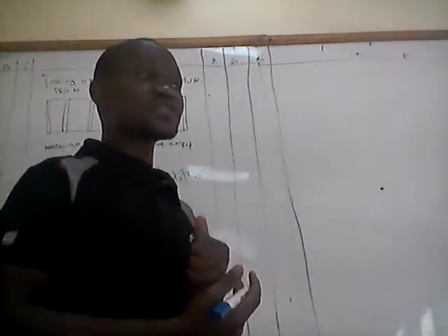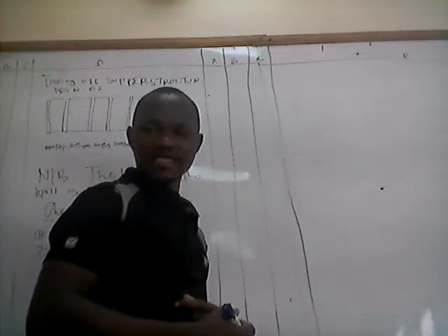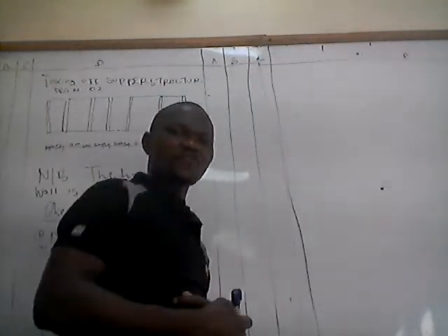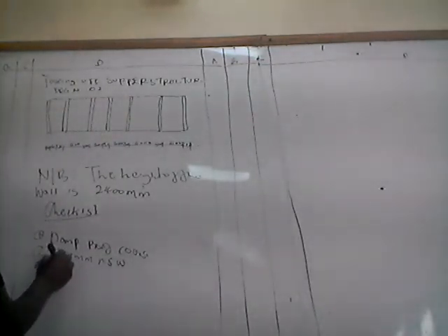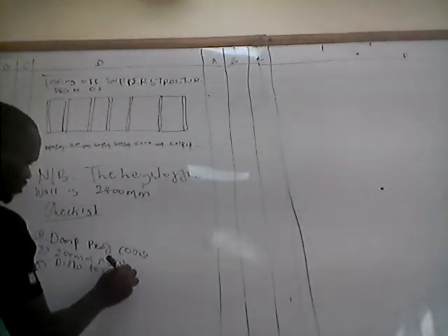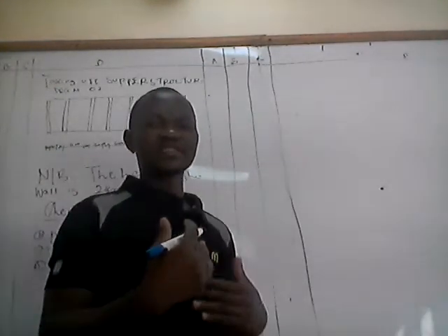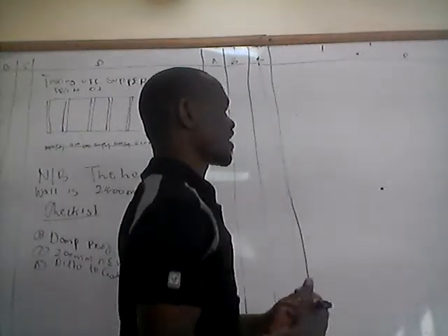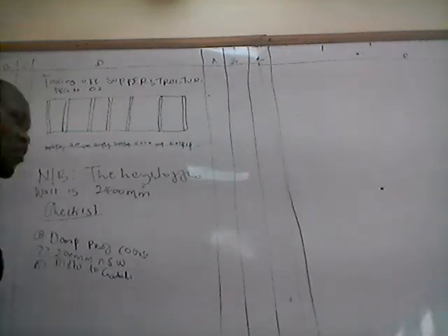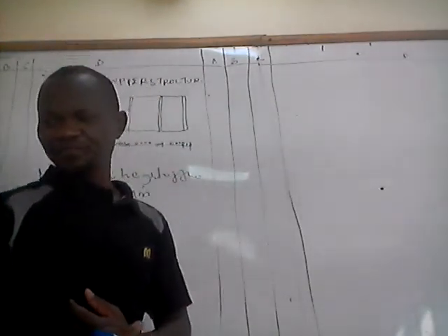Then let's assume that this plan is of a gable, or the structure is of a gable. So you have to say ditto to gable. When you say ditto, it simply means above. You are measuring the same as what is above. So instead of writing 200 millimeters walling to gable, you say ditto to gable. The examiner will know what you are measuring again.